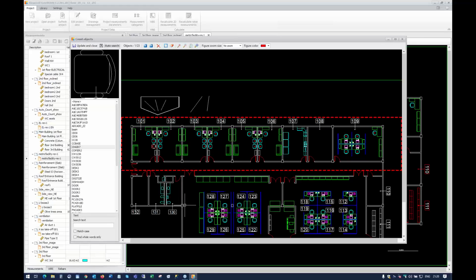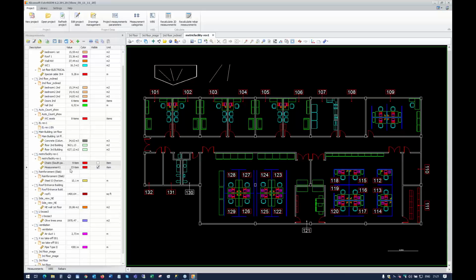So we can combine the search in order to count blocks that have that text attribute. You just type the text here and it finds and it counts only valves that are half an inch or 3/4 of an inch. Or if you leave empty that field, you will count all blocks valves. So you will count all of them. If you update and close, this measurement is passed here, so we have counted 23 items.